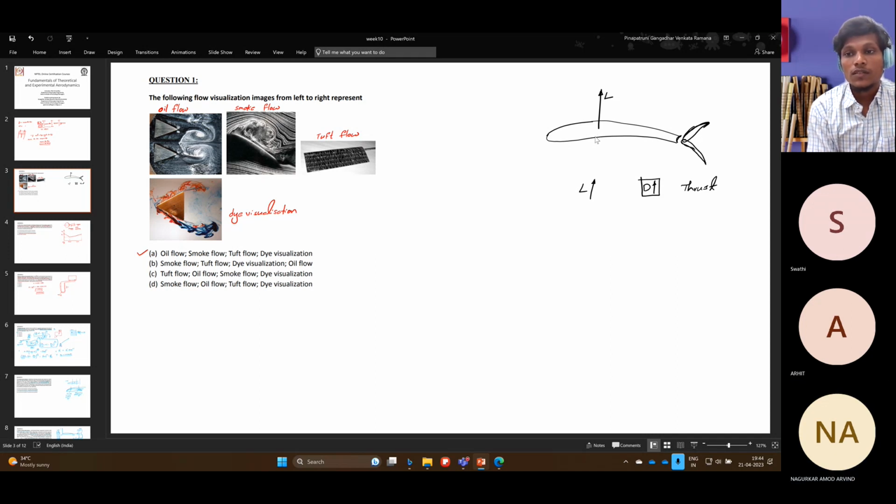One problem with deploying in the downward direction is that it increases the lift, because you are increasing the camber. Assume it is now at a velocity of, say, 30 meters per second, just an approximate value. Now you deployed this flap in the downward direction, and let's assume the velocity comes to 25 meters per second, as you said, to decrease the velocity. But the corresponding increase in lift will be higher, right? Which is not at all required during the landing.